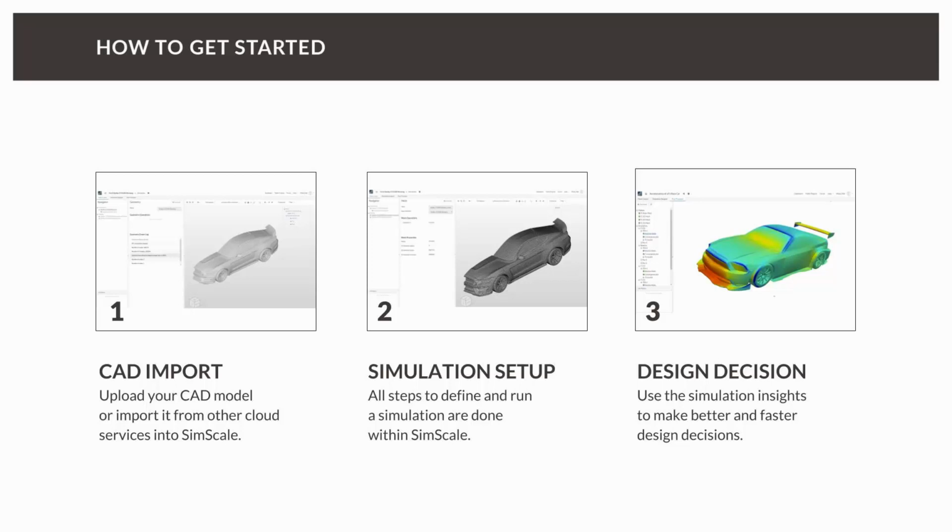However, the great thing about SimScale is that it uses a meshing tool called snappyHexMesh, for example, which is very robust regarding problems with your geometry. But as I mentioned, try to make your model as clean as possible in your CAD system. Then you upload your model, and the next step you need to do is what we call meshing.